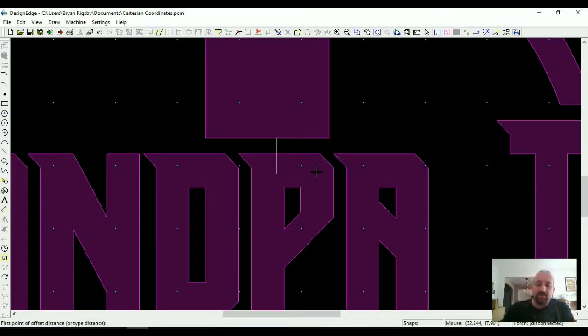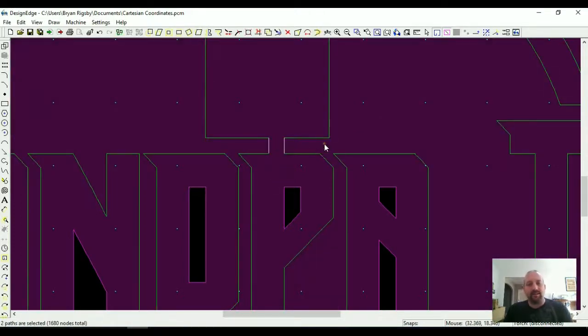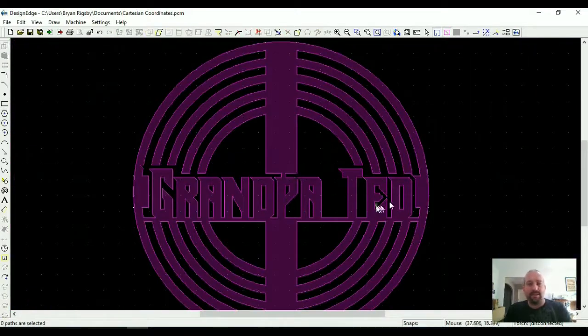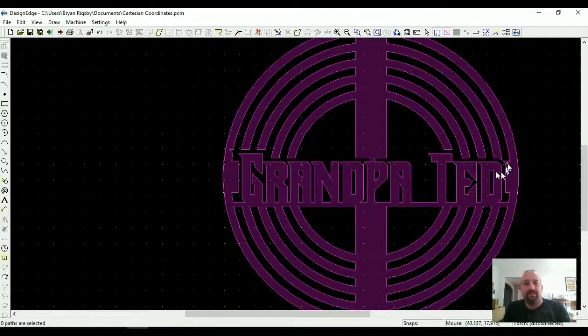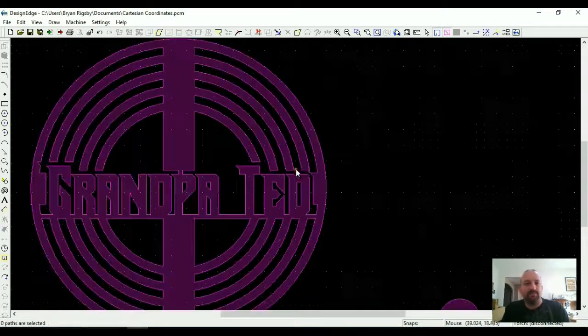So if I want to move it over 1/8, I push 1/8, hit enter, pick a path and control to copy. So I'll hold control for the first one, let off, let it move the second one, and I can trim that out, and that will hold that steady. I think if I cut this out of material, it'll all be just fine. So thick enough material, I don't really want to connect the tops. I'll just let those hang.